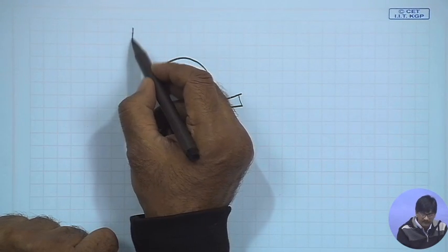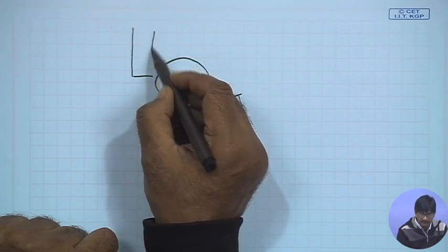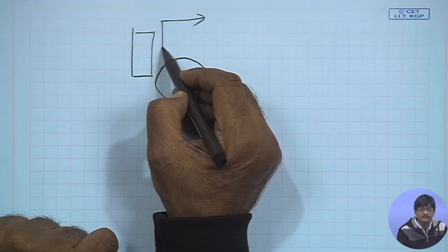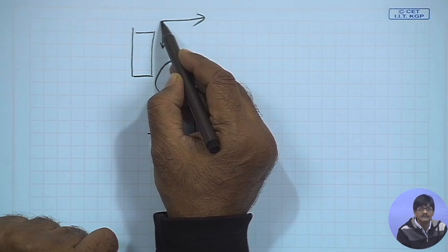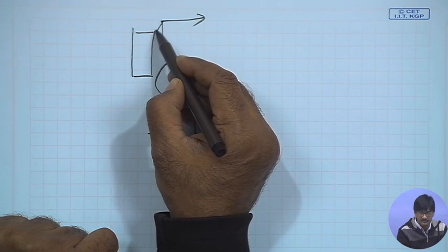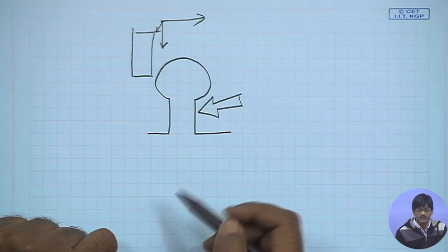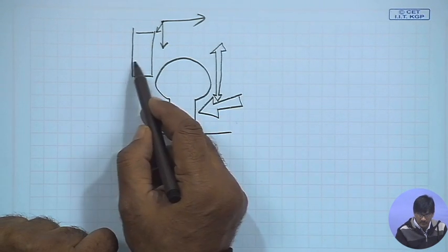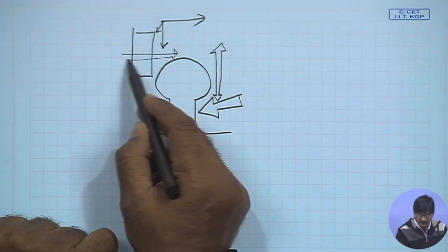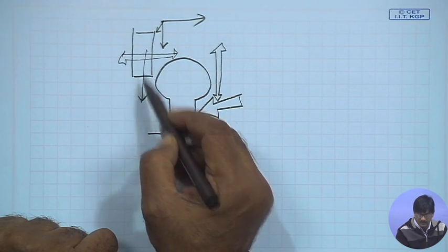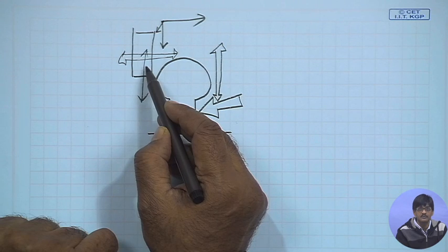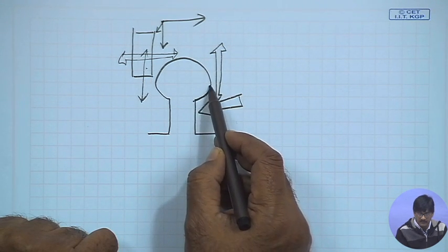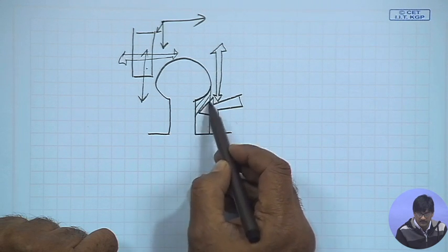Because if you have an ultrasonic tool here, and if you have a 3 axis machine which can make movements in these 3 directions, it can move down, the tool can move sideways. So, sideways, up, down and out of the paper into the paper. In no way can it reach, it has no way of reaching this particular space.